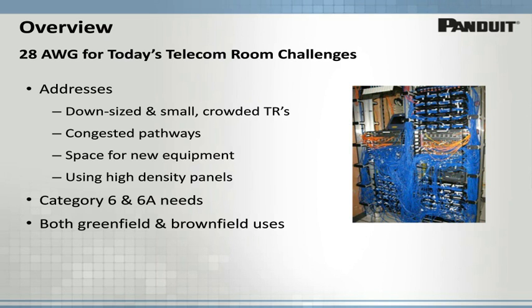Therefore, as we try to solve these issues in the TR and data center, we will be looking specifically at the role 28-gauge patch cords can have in addressing the space challenges. And just so you know, 28-gauge cabling can also be used in other portions of the channel with many of the same benefits, but since our focus is within the TR and data center, we'll focus on patch cabling today.